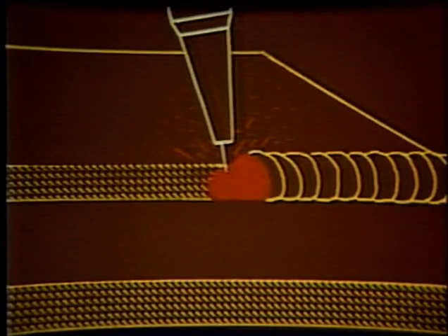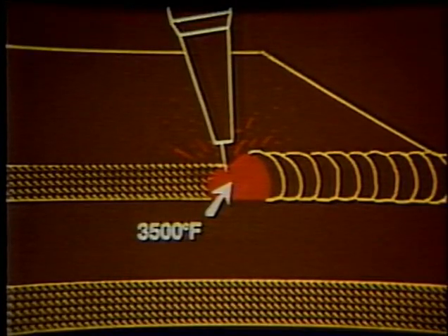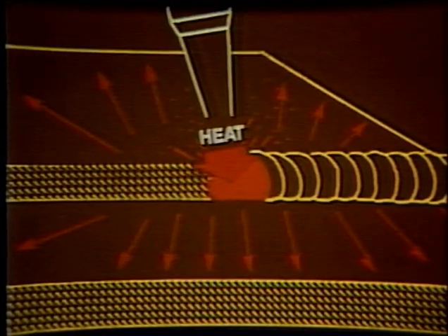Understanding the amount of heat input for a given weld length will also aid in devising strategies. The total heat input must be balanced to produce the desired weld. It is estimated that the temperature of the molten steel in the puddle is about 3,500 degrees Fahrenheit. Extra heat is required over and above the amount needed to melt the filler metal and the base metal surface in order to compensate for the heat that is conducted away from the weld.